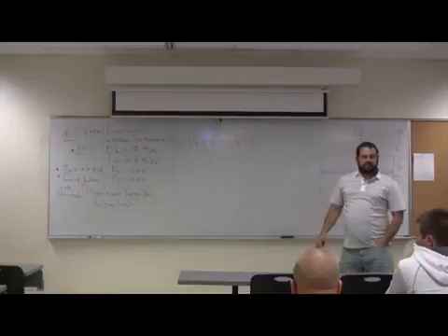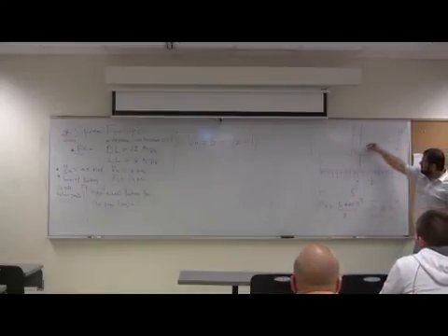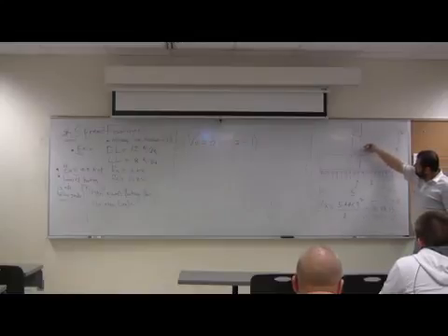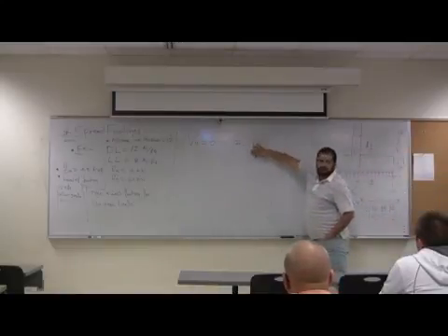Where do we calculate the ultimate shear? Here. Where do we calculate it? At D. Not at the face, actually, we're going to do it in a minute.